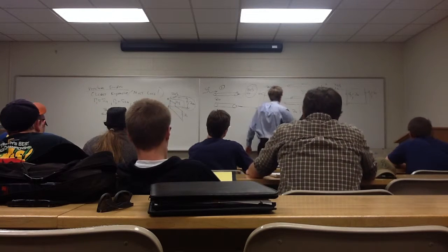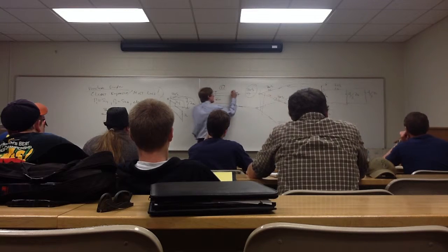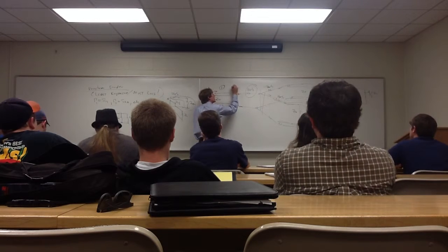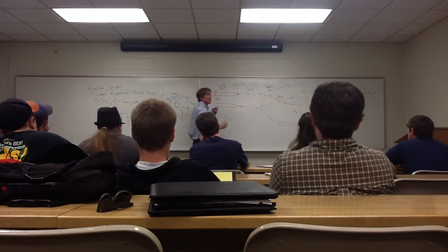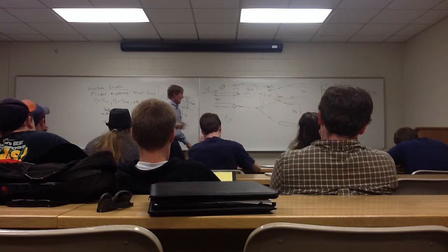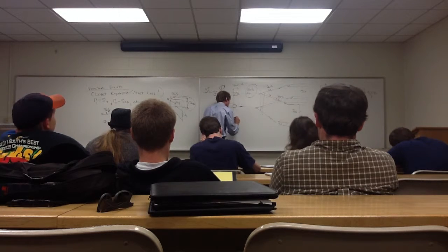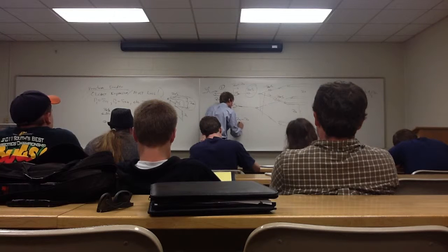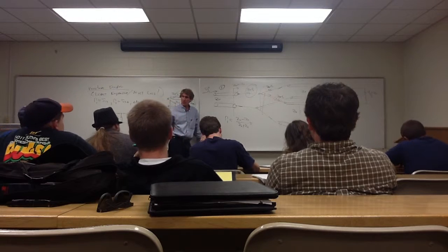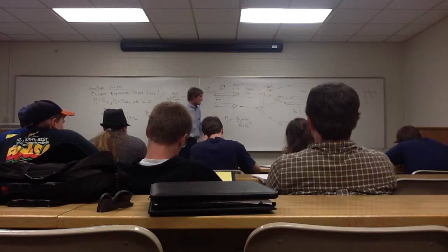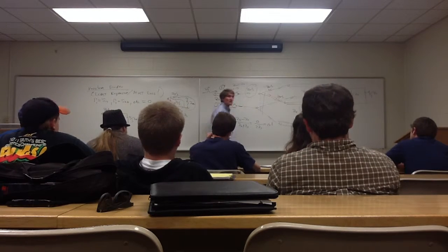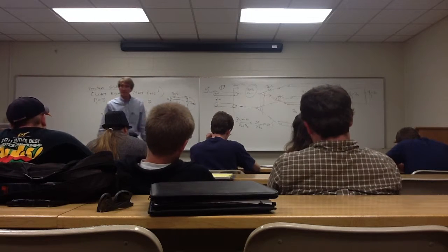What's the reflection coefficient looking into this point right here? In port 1, if I'm looking into a value of Zn equals Z naught, class, what would it be? How do I calculate it? Always, I take the impedance I'm looking into, Zn minus Z naught over Zn plus Z naught. Do you agree? For the reflection coefficient, well, what's Zn? Just say it. Z naught. So it's Z naught minus Z naught, or 0 over 2 Z naught, or it's 0. Thus, no reflected energy. That's the idea behind this whole thing.